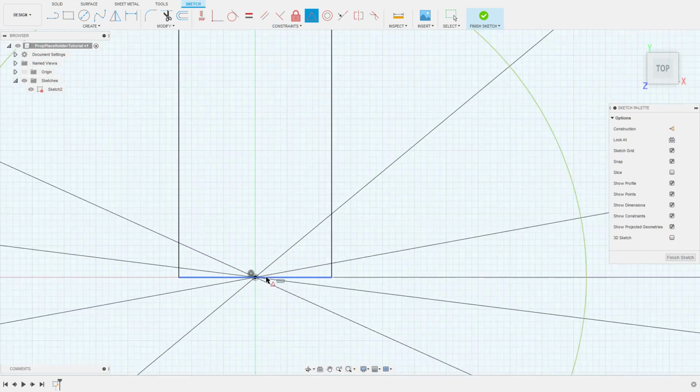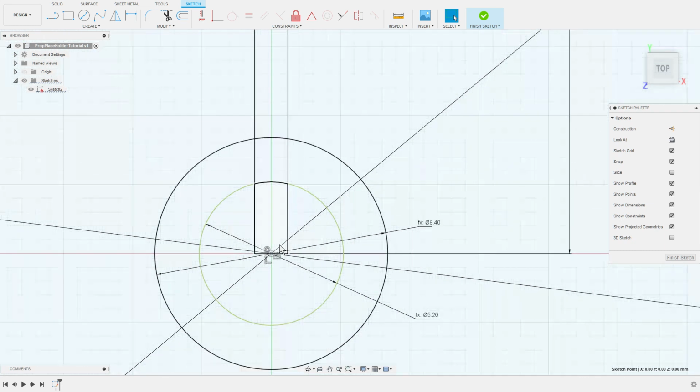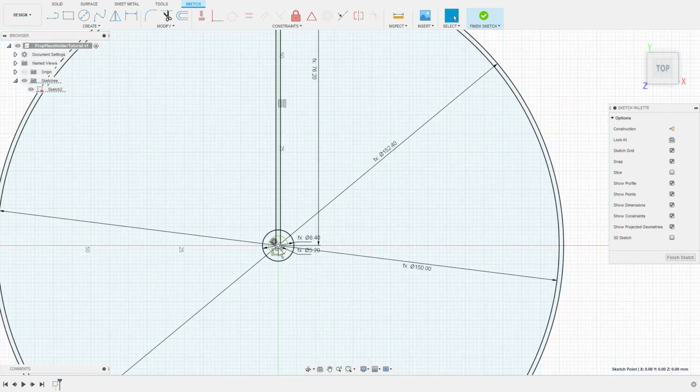And it does a couple of other things. When you say you want a midpoint, you're telling it two different things. You're telling it both, A, you want this line to be coincident, in other words, share a point with whatever point you're selecting, but that you also want that point to bisect the line. So that's what midpoint has done. It both centers it side to side, if you will, and makes sure that it's on the line up and down. All right.